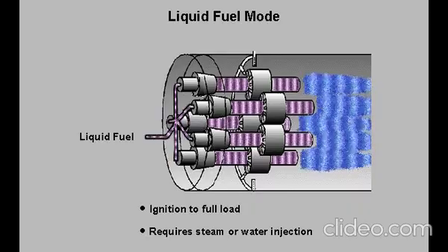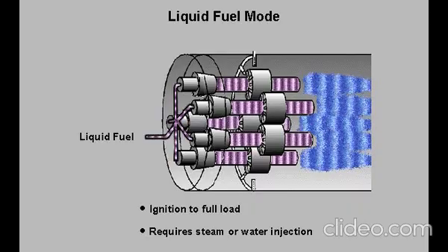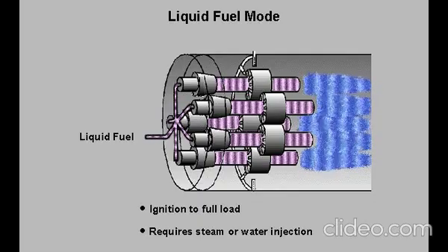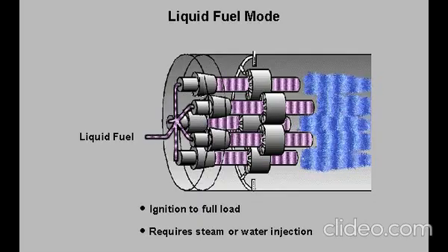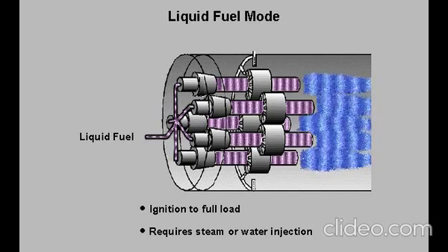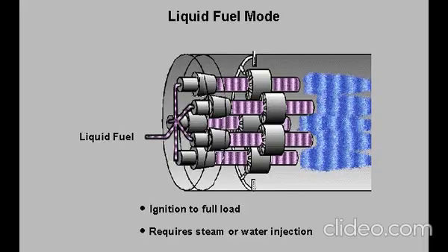Liquid fuel operation requires steam or water injection to reduce NOx emissions. In addition, without steam or water injection, the turbine cannot be operated above a certain load capacity. Without steam or water injection, the combustor exhaust gas temperatures will exceed the design limits of the first stage nozzles.